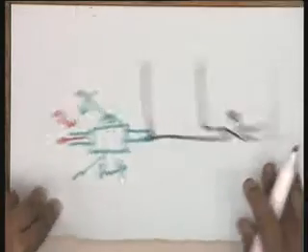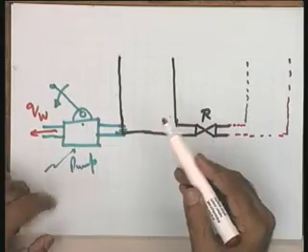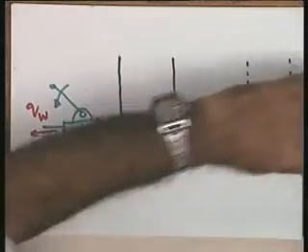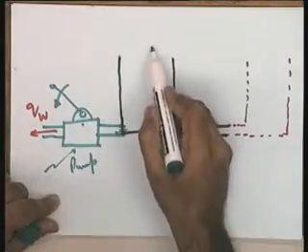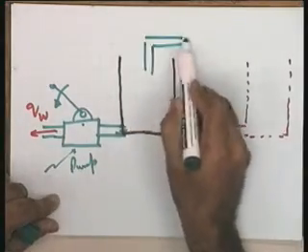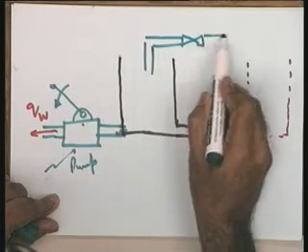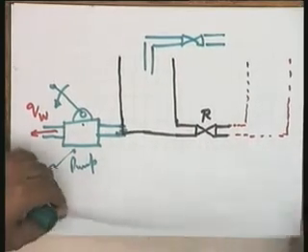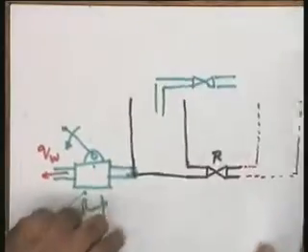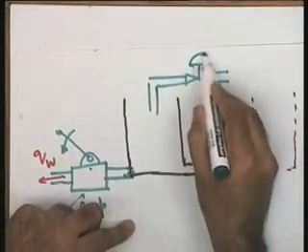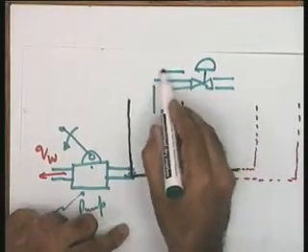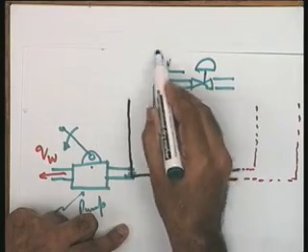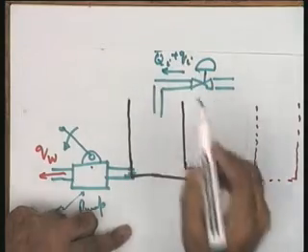Okay? Now what is the flow which you are going to control, or the manipulated flow? The manipulated flow to the tank is going to be through this particular valve, and this particular valve, I will put it this way, is a controlled valve. So it means it has got X, the opening which you can control, and let me say that the flow is QI bar plus QI. Now please develop the equations.